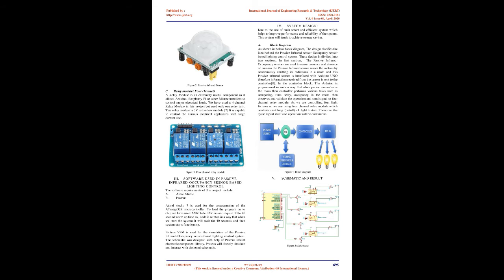3. Software used in passive infrared occupancy sensor-based lighting control. The software requirements of this project include A. Atmel Studio, B. Proteus. Atmel Studio 7 is used for the programming of the microcontroller. To load the program onto the chip we have used AVRDUDE.